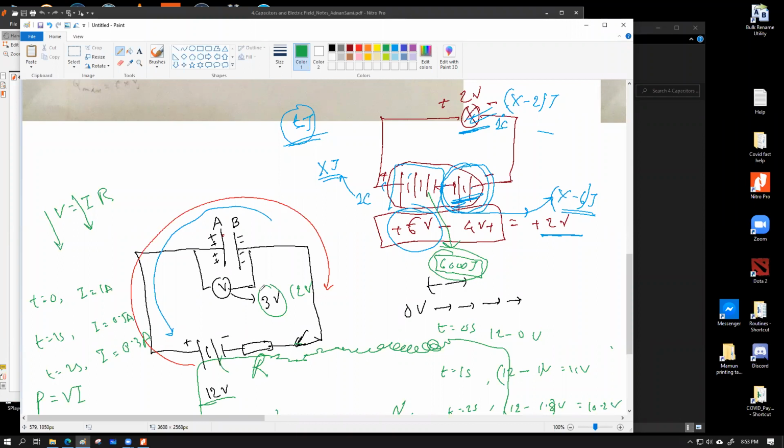Theoretically, this process is going to take forever because this is a negative exponential curve. But for practical purposes, we don't ever measure a current up to an infinite number of decimal places. So, as many decimal places as our device shows, until we get 0 there, we can take it as 0. That might actually have a finite amount of time.